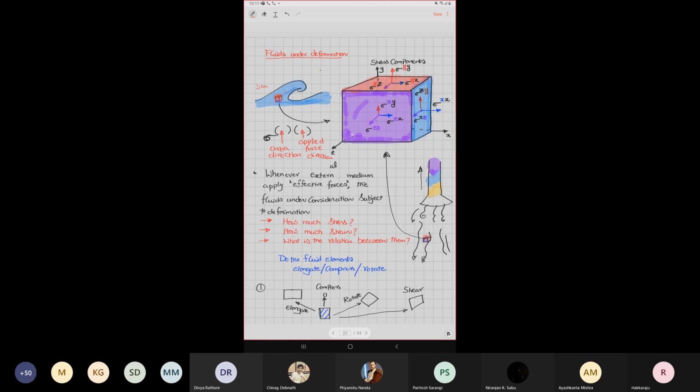And here, what we are trying to look at is, pick any of the surfaces and try to write down stress components on the surfaces. The first subscript is always the normal direction of the area. And the second subscript is always the force direction. That means if there is a force normal to that plane and the plane normal is also in that direction, we will call it sigma xx. So only that kind of force on that area gives me that stress component normal to that. Similarly, forces can be acting parallel to the surface also.